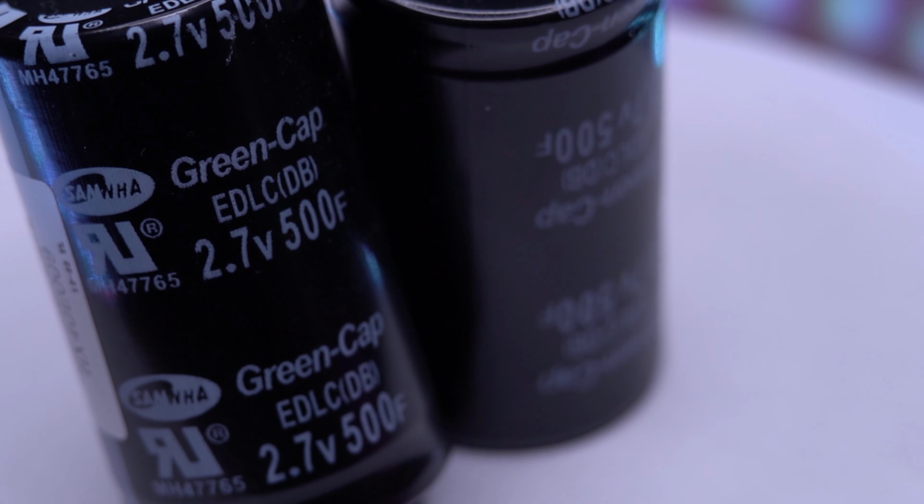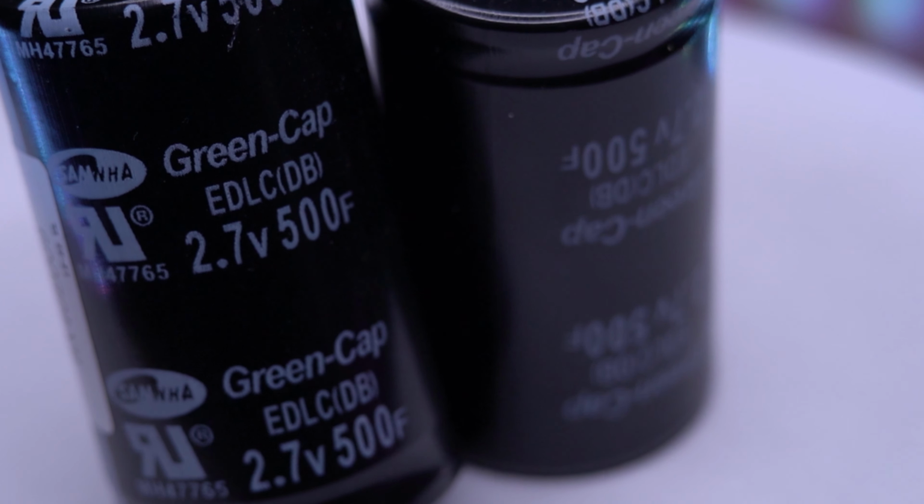A similar approach could technically also be done for memory that relies on capacitors to store information. If you find that the radiation particles are changing the charge states in your capacitors, simply use larger capacitors that can store more charge. You can also use higher voltages and more current. Of course, the disadvantage of either of these techniques would be that your memory would become very huge and take up a lot of space, and a lot of power, and it would be slow.